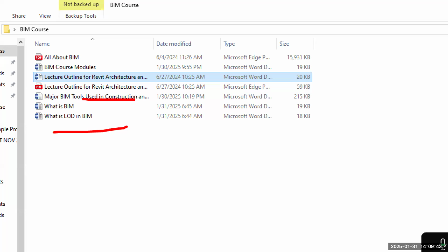As you mentioned, the rendering part will be Enscape, Twinmotion, etc. Briefly, it's within BIM, but we are not going to talk about that tool. To install Lumion, the system requirement is a minimum of 32 GB RAM, a dedicated graphics card with 8 GB, and a high-performance system.